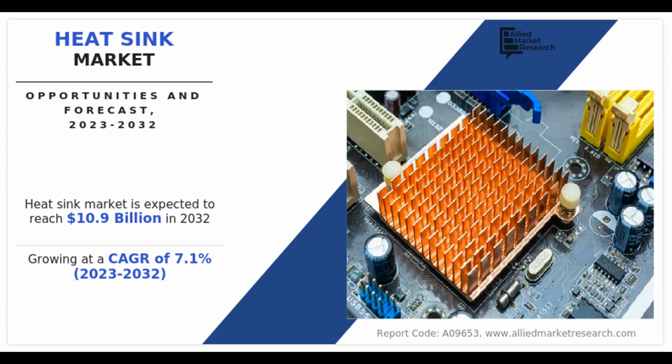The die determines the cross-sectional profile and overall shape of the extruded heat sink. Cooling and finishing. As the material passes through the die, it undergoes rapid cooling, solidifying into the desired shape. After extrusion, the heat sink may undergo additional processes such as cutting, drilling, or surface treatment to meet specific requirements.